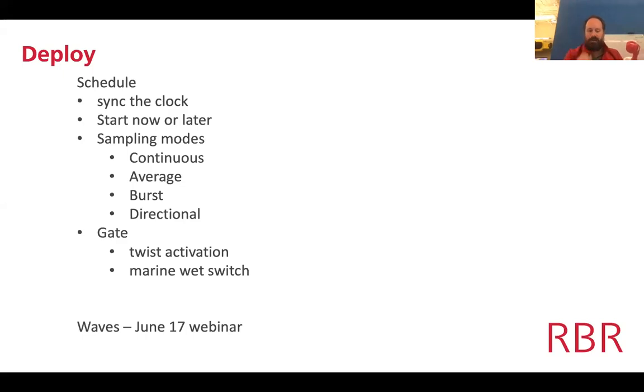But of course, we can't predict in advance at what time of day or how often the wire walker will move up and down. And so the instrument itself can be told, when you're moving upwards, I'd like you to sample at 16 Hertz. When you're moving downwards, I'd like you to slow down and go to sleep, save lots of power, and only sample maybe once every 2 or 3 seconds. That will result in a data set that has 2 different sample rates in it. And this is really trivial to do, and means that you save a tremendous amount of power. Usually upwards of 50% of the power can be saved that way.